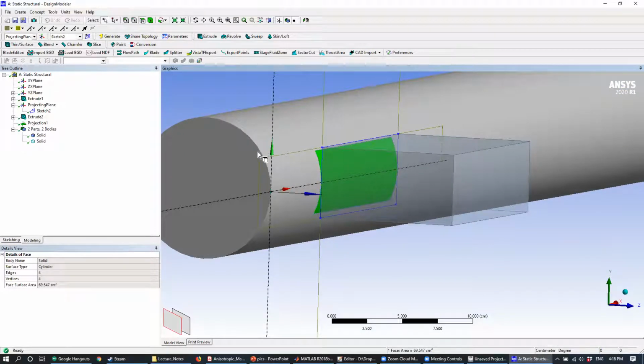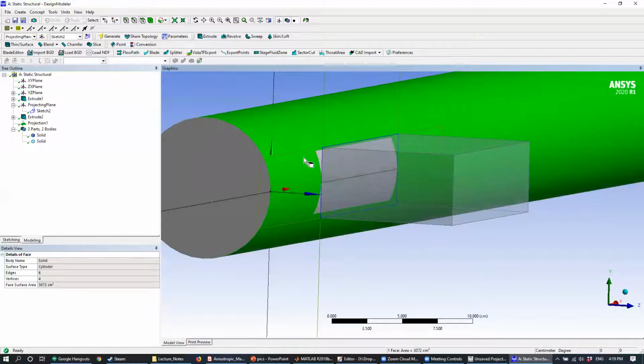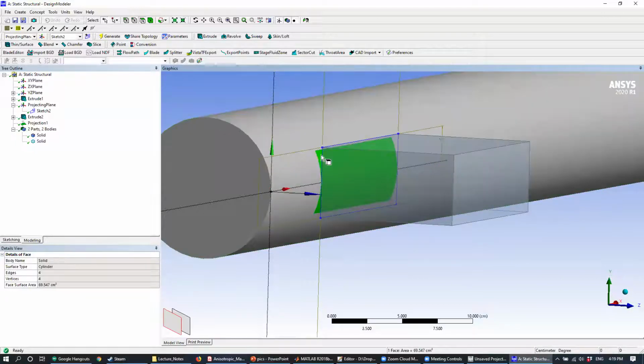Because I know when we did Ansys Activity 3, there were some people that had some issues with that thin strip. Because if you remember from that activity, we had to specify a thickness of that strip, and depending on the thickness, it actually changed the results quite a bit. So obviously you don't want that. You don't want your fake surface or your phantom surface here to affect your results in any way. So in this sense, this is a little bit cleaner because this just creates something that's selectable without actually introducing any new physics in the system.